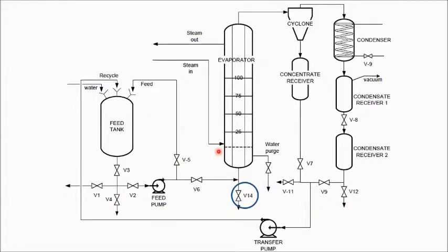After 15 minutes, you can collect the evaporator sample. Just easily open V14. Measure all volume and record the refractive index for all samples taken. Make sure to return all the samples into the feed tank.